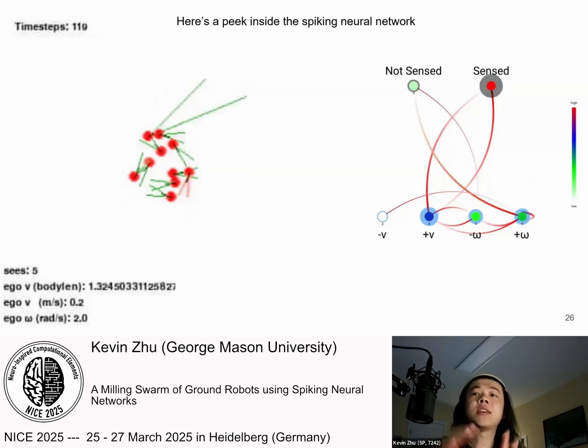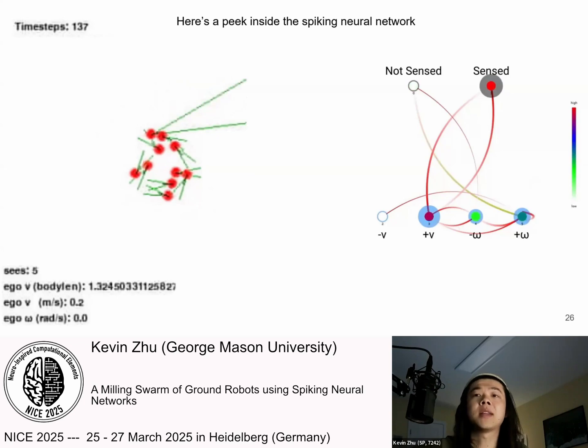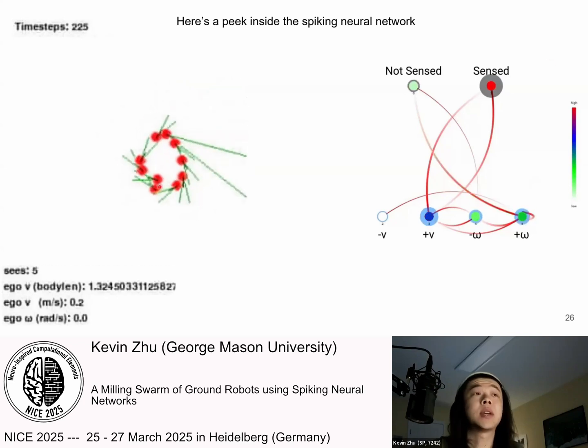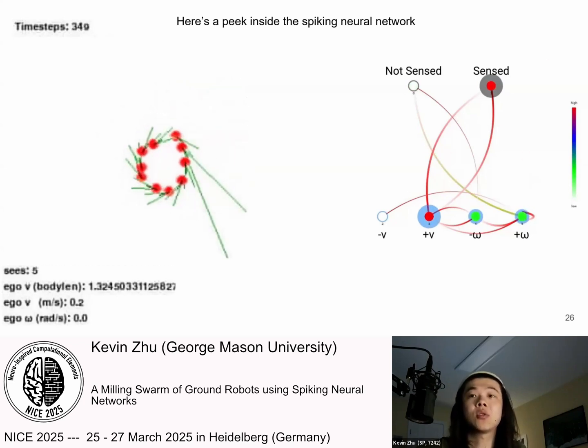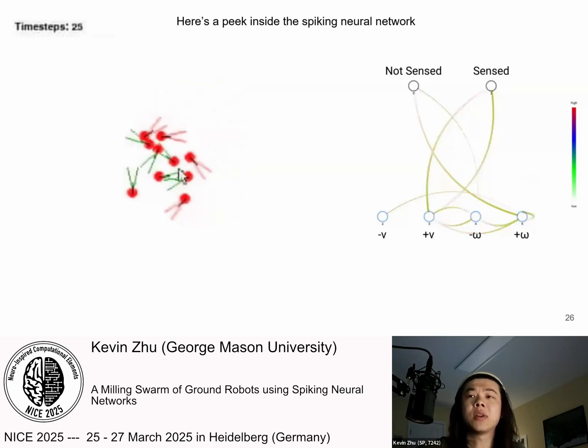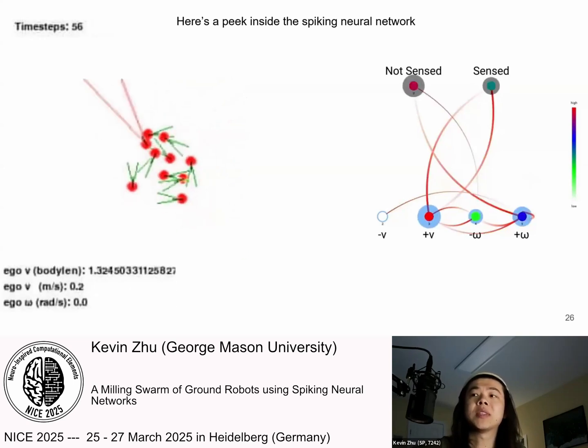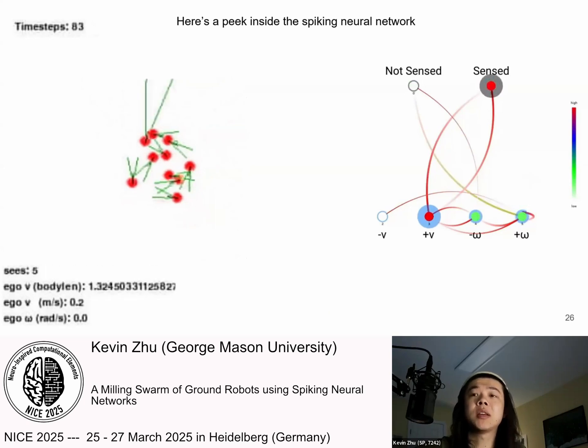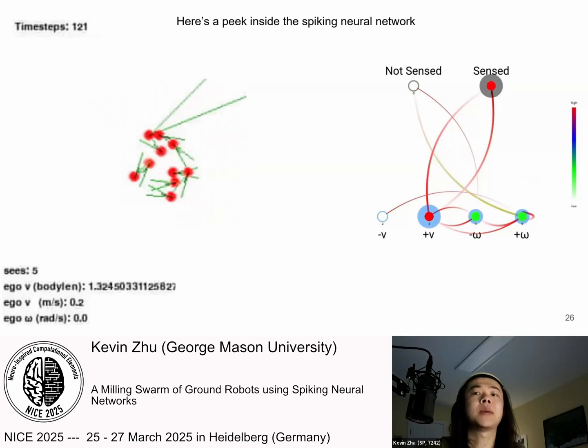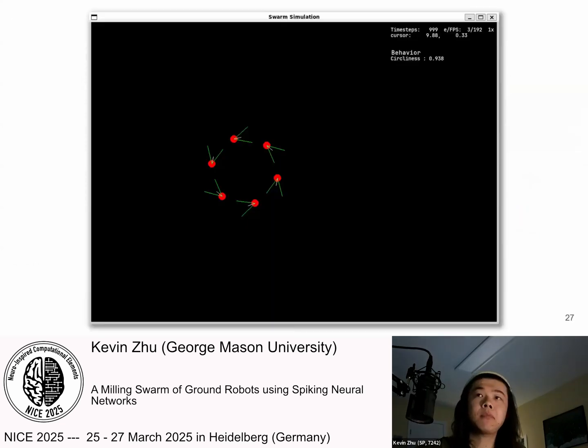And just to be clear, this is a human-specified encoding and decoding setup, so the action space here is defined and not learned. What is learned is how to connect the input, the sensor data, to the control output. Here's also where the sim-to-real connection comes in. We give each robot the same FOV and sensing range as those we measured, and we also performed a linear mapping of the number of spikes received to the speed and turning rate based on the measurements we took earlier.